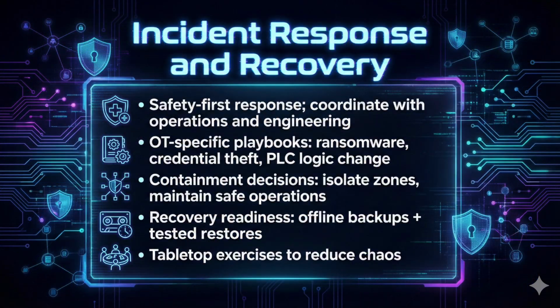Incident response in OT must be safety first and operations aware. The classic instinct in IT, pull the plug, can be dangerous if it interrupts a critical process or disables safety functions. So we plan OT incident response with engineering, safety, and operations at the table. NIST incident response guidance emphasizes integrating response into broader risk management. And in OT, that means having predefined decision points.